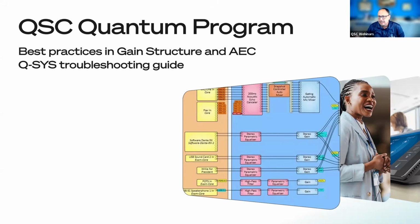The idea is that gain structure is the root of everything across the board. Any of you using our ACPR, that's not going to function well without having your gain structure set properly. Acoustic echo canceling too: if you don't have your gain structure set right, you're going to have challenges with that. It's one of the very first things, and the reason we run this every couple of months is because it's one of the things that our support people constantly tell us. So hopefully you get something from this.